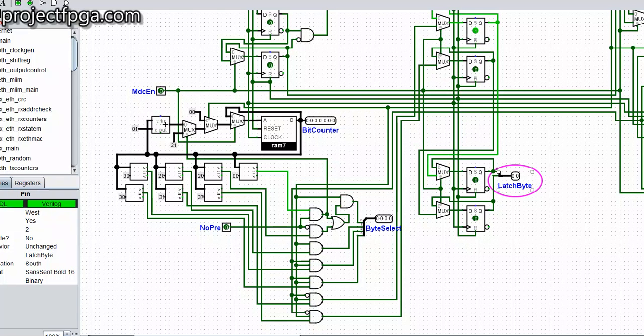So it all starts from here. This is the condition that sets them from here and here. They move into these 2 multiplexers. When this clock is enabled, they move into the flip-flop, this one and this one, and from there you enable the clock again. Then they move into here and here. So the last byte upper bit and lower bit, this is where they are being generated. So let's see the conditions for them.